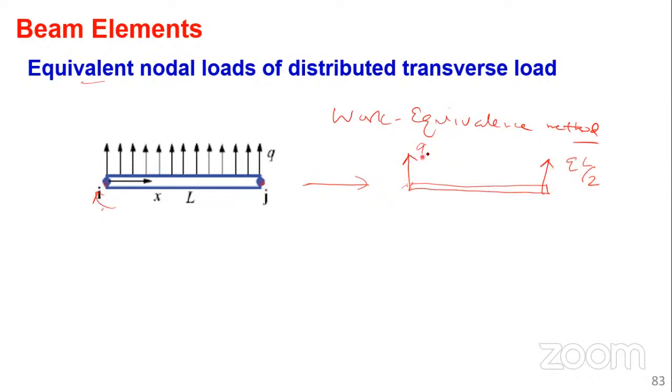The shear force, of course, we are taking half of this. We multiply by half the L. We are taking this load multiplying by this length, which is L over 2. Then we apply it here, and we apply it the same way we deal with our applied load, the UDL, for the normal type cases of analysis of structures. Then for the fixed end moment or the reaction, we use the sign convention for the beams.